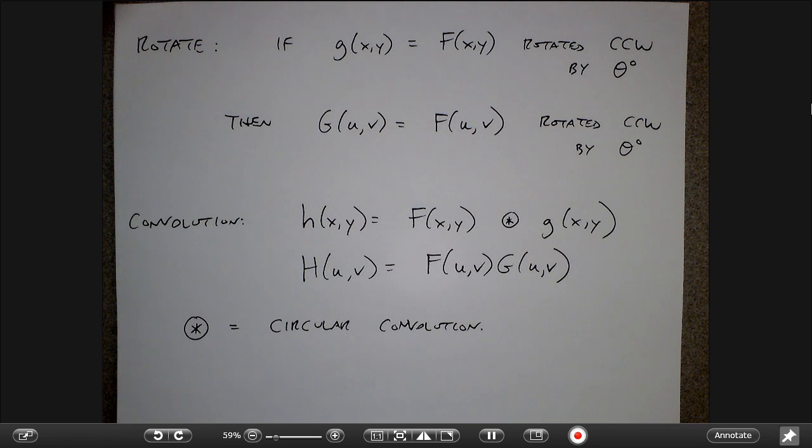So again, whereas in signals we kind of hit you with the idea that for efficiency we always use the Fourier transform to do convolution, I don't think in image processing that's always true, because the image processing filters are often pretty small. So while this is true, it may not have as much functional importance in image processing as it did behind the scenes in signal processing. Okay, but it's good to know.